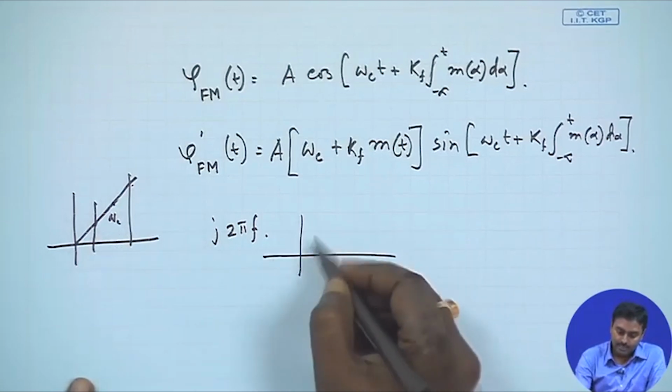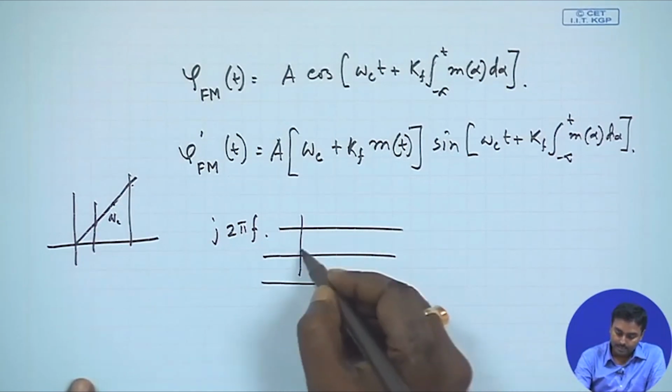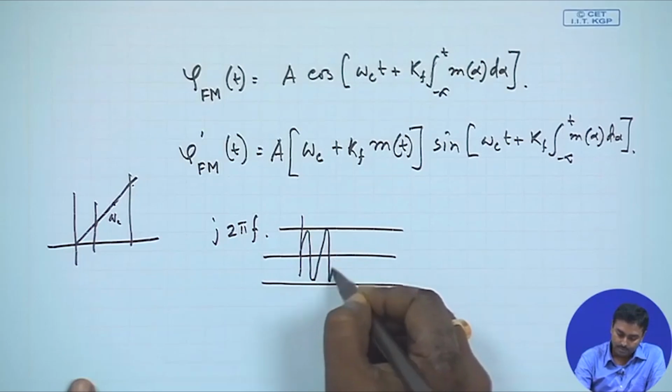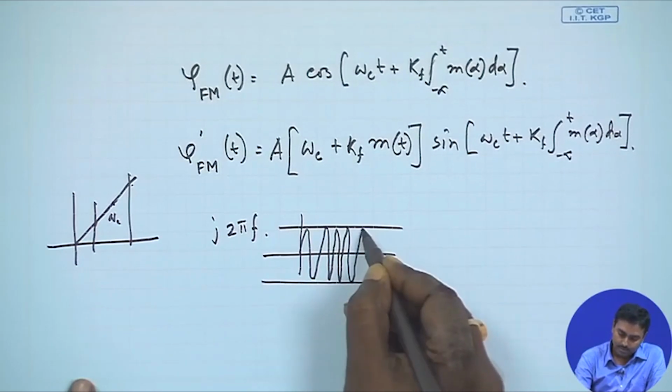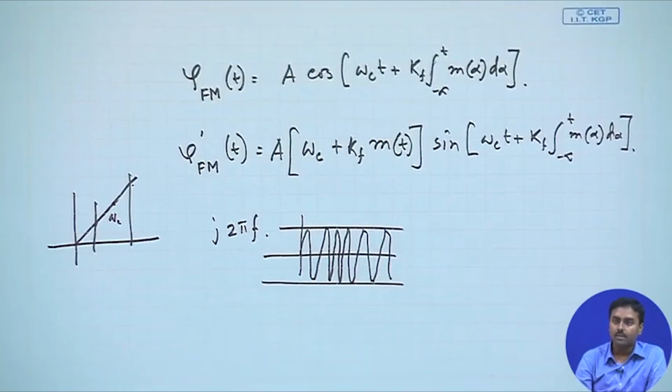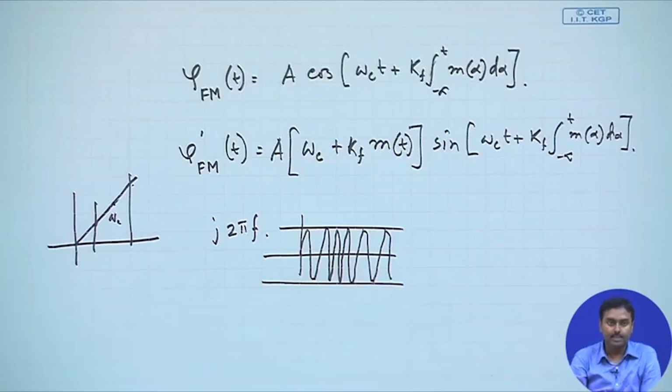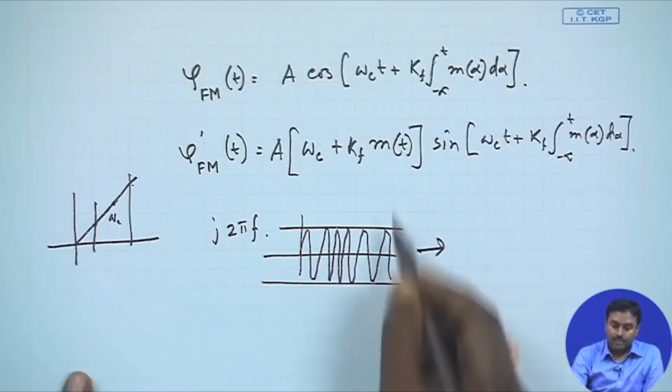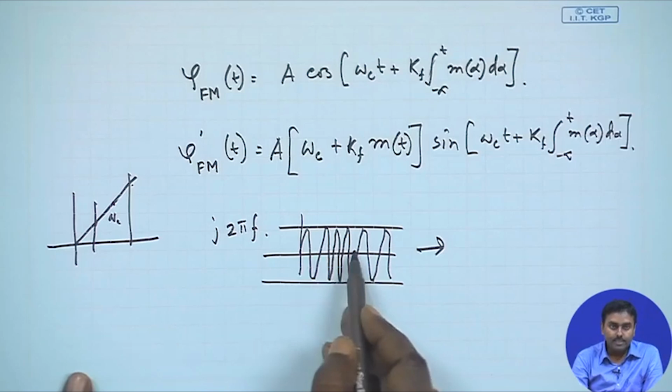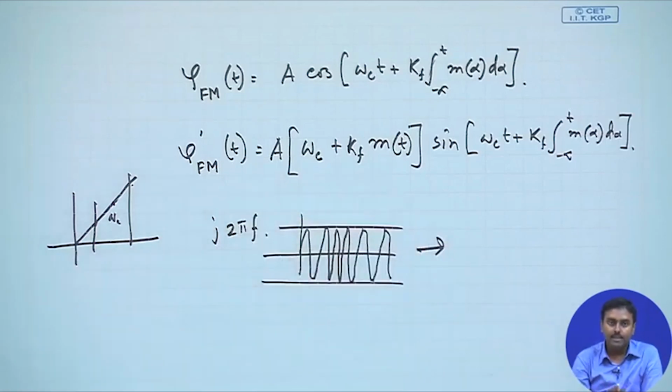So, I had initially an FM modulated signal, which had some modulation. It was varying with respect to the amplitude, it is just the frequency deviation. If I just differentiate, this frequency variation also comes into the amplitude. Whenever there is a higher variation of frequency, I will have a higher amplitude, and correspondingly if there is a lower variation I will get a lower amplitude, right.